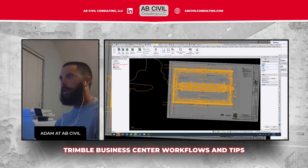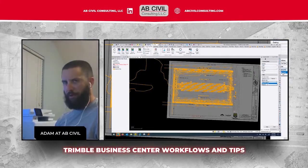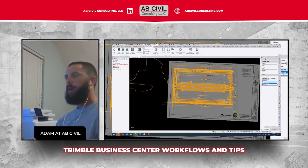Hit Google Earth, and then it allows you to adjust the northing and easting, which you might want to do. After you bring it into Google Earth, you can adjust that if you want to tweak it a little bit, left and right, up and down. I always hit clamp to ground. And then you hit apply. It should bring Google Earth up.